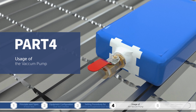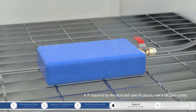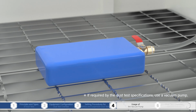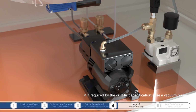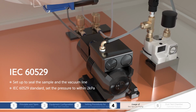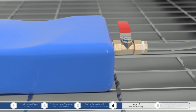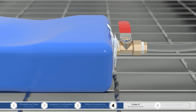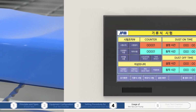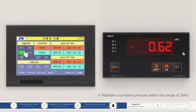Part 4. Usage of the vacuum pump. When the vacuum condition of the sample is required according to the dust test specifications, a vacuum pump is used. Let's take the example of the IEC 60529 test specification. According to the IEC 60529 standard, connect the sample and the vacuum line before the test, and set the pressure to within 2 kilopascals. Press the vacuum pump button, and if the pressure on the pressure gauge remains consistently within 2 kilopascals, the sample sealing is successful.